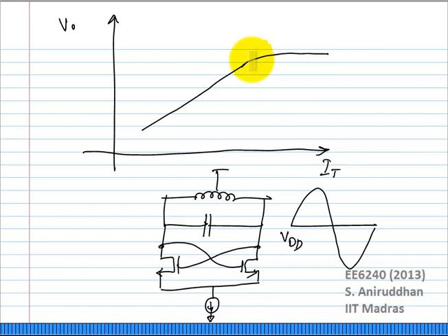Okay? So let us say you increase current till you operate at the maximum possible amplitude of the tank. Or, if I look at it in a different way, for a given current, I want to choose my RP such that for the VCO I am in this region.